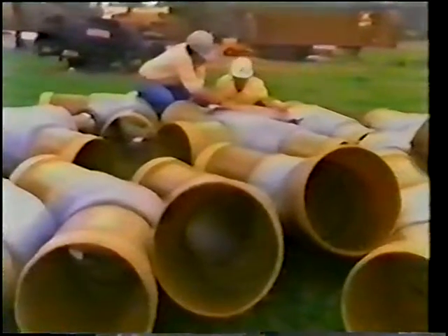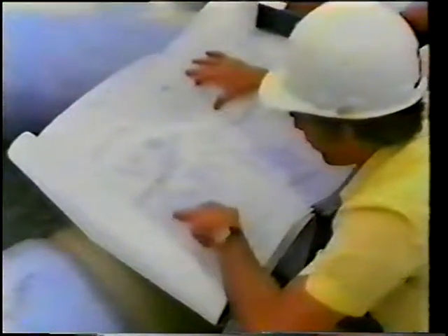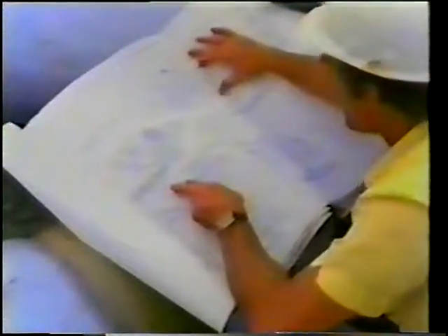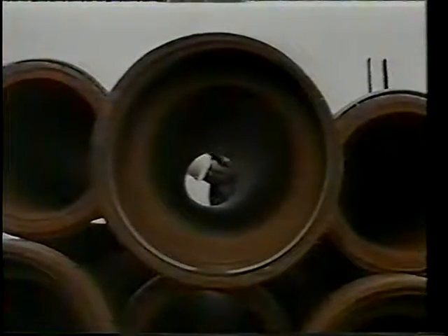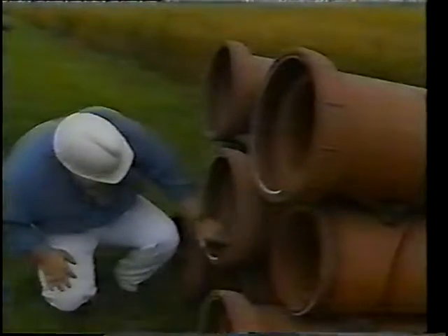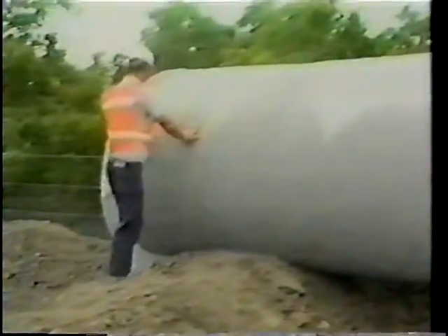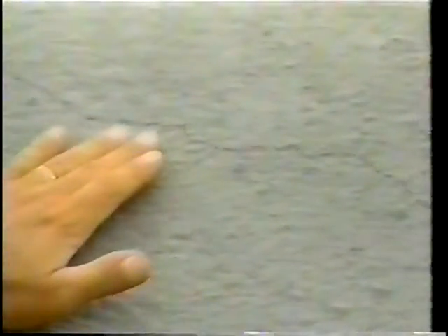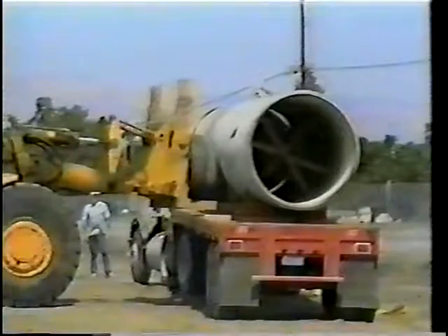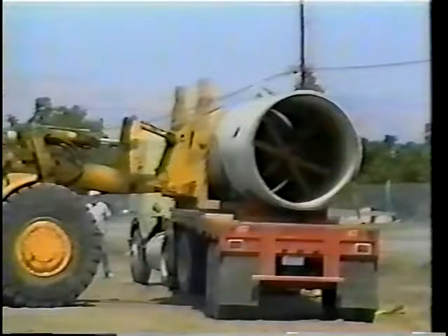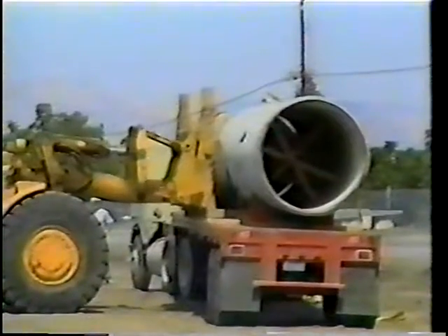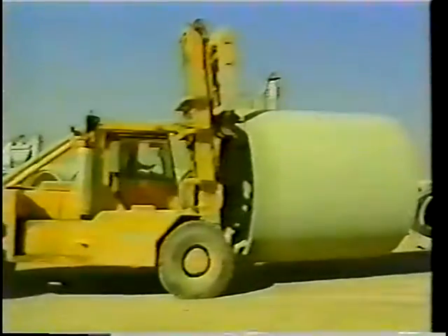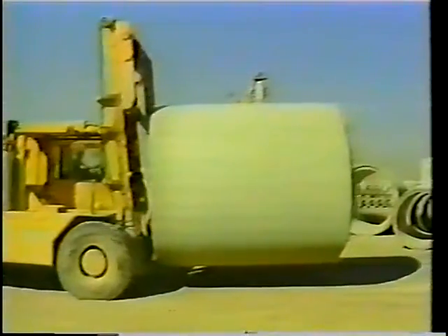Pipe size and class must be checked against the laying diagram or specification drawings. Pipe should be inspected for any damage incurred during transportation. Pipe that are lined or coated have to be checked for possible damage and any cracks evaluated. Throughout the project, it's important to follow procedures for the safe handling and storage of pipe, gaskets, and fittings.